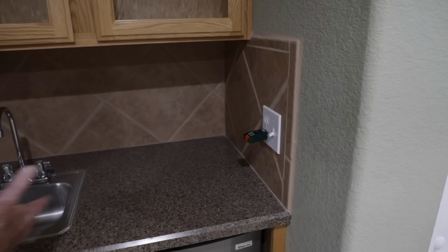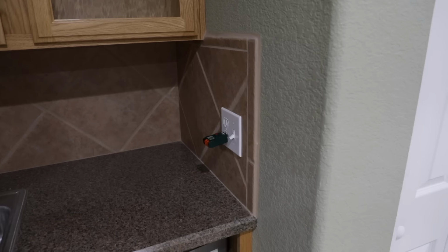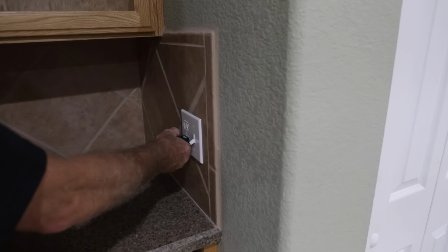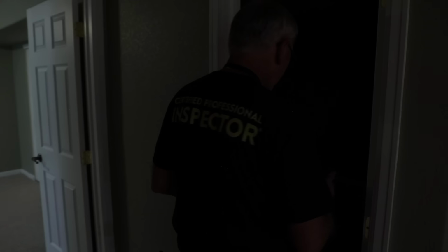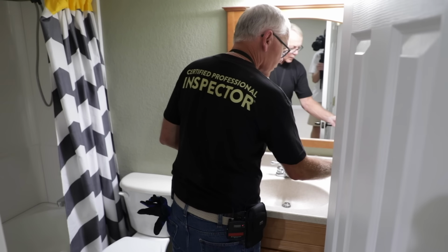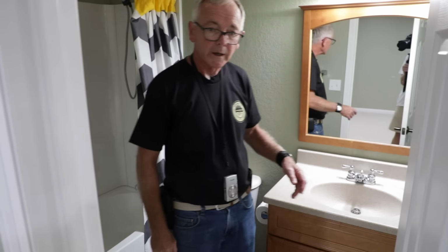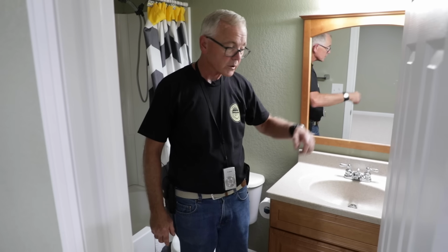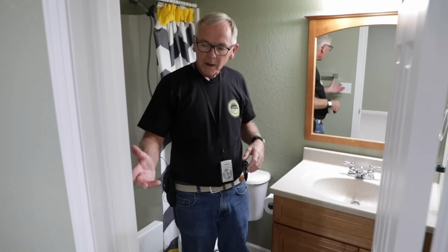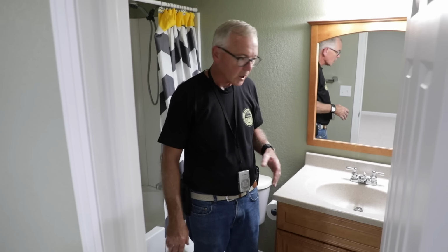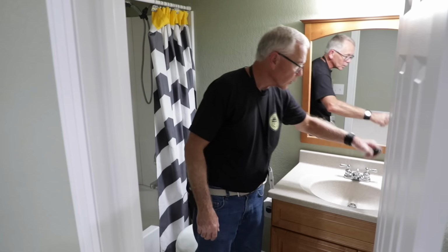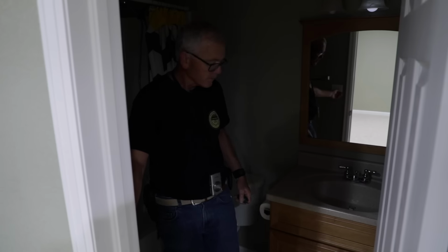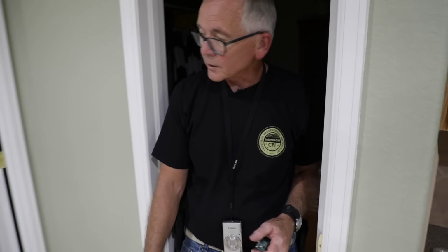We've got a bar sink here that I'm going to test because it's close to the water. This should be GFCI protected, and it is. So let's go in the bathroom in here. Uh-oh. Bathroom light is on the GFCI. So we verified that this GFCI is working by testing that other receptacle in the bar sink. Having the lights on this circuit is no problem. That's pretty common. So we're going to go ahead and note that this one is correct. We still have to find the GFCI for the main floor half bath.